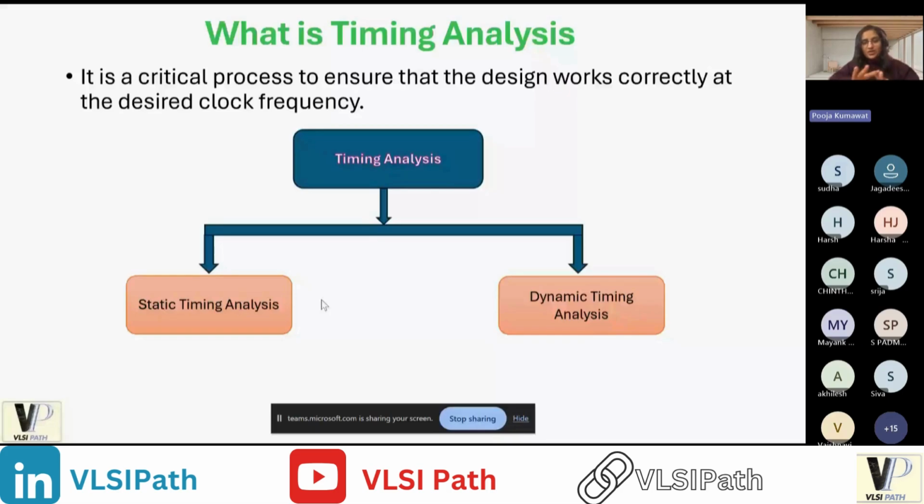We will take all the delays of the nets and cells, and there we'll check the critical path that has the maximum delay, excluding the false path and multi-cycle path. We will discuss those things later. So in the STA, no input stimulus required, meaning all the analysis will be on the given net delay and cell delay, which we will consider irrespective of the input stage. From the given design, we will take those delays, perform the analysis, and try to optimize the delay on those particular cells.